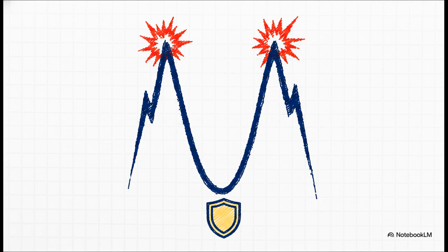By adding a second mass, we gain this beautiful deep valley of zero amplitude exactly at our operating speed, right where we need it. However, because it's now a 2 degree of freedom system, we've basically split that original peak into two. We now flank our safe valley with two dangerous new resonant frequencies, omega 1 and omega 2. If the machine ever speeds up or slows down through those exact points, the amplitude spikes to infinity. We have to avoid them at all costs.